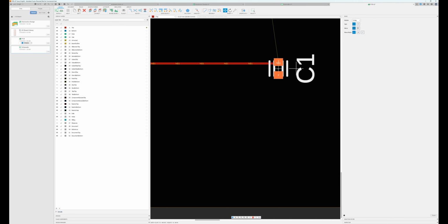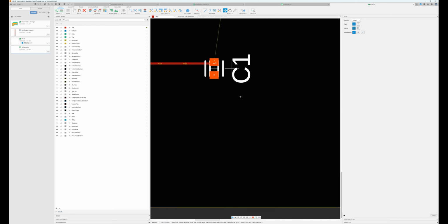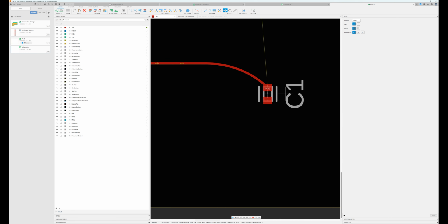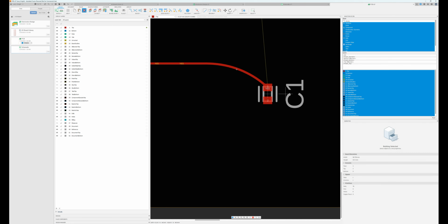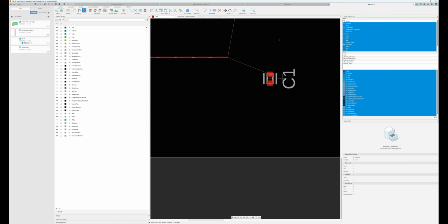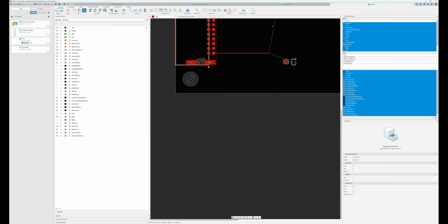This is where it becomes your project. So we click on that. Oh, we've got to come up here to move. We click on that, and then we can move it however or wherever we want it. And if you don't like the way it is, then you just come over here to the X and click it, and it's gone. And you never lose your connection to your schematic unless you delete it on the schematic. But the PCB always follows the schematic.